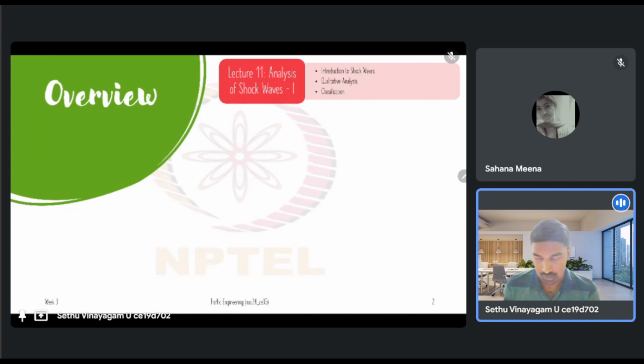So in the previous week, we learned about the traffic stream parameters, right? So we learned about the flow, density, and the stream speed, right? So Q, K, V. A combination of these traffic state variables, traffic stream variables, will define what we call a traffic state, right? For a given value of density and given value of flow, we have a particular traffic state. It's a traffic condition that we are describing in terms of these traffic variables. So that's what we call a traffic state.